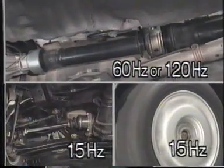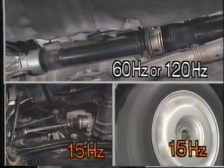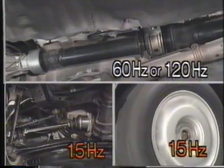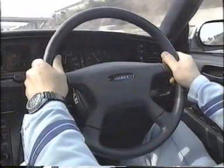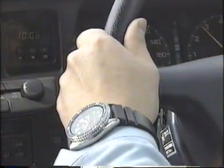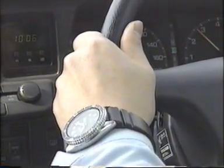This indicates that the vibrating force is generated by the tires, or by other components that are turning at the same speed as the tires. If a vibration frequency analyzer is not available, there are other methods that you can use to estimate the parameters of a vibration. All you need is your hand and an intuitive knowledge about the most commonly occurring frequencies.